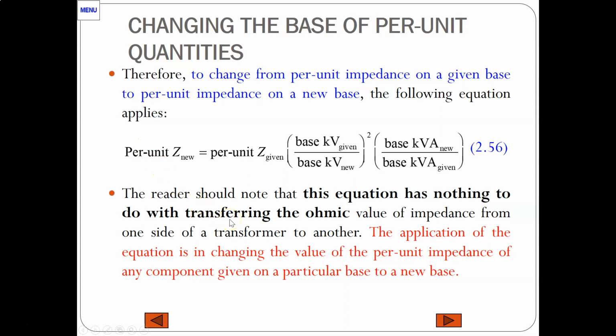So, as I said in the book, the reader should note that this equation has nothing to do with transferring the ohmic value of impedance. We are working in per unit. You're transferring the per unit value to another per unit value.